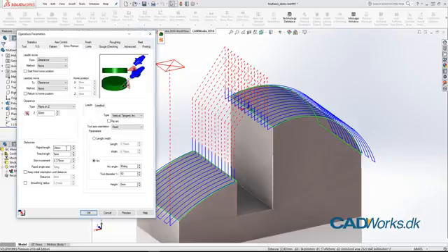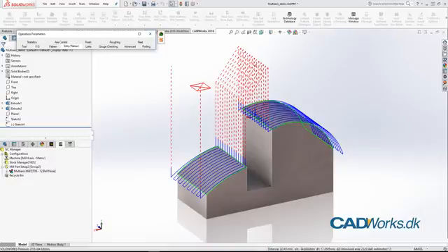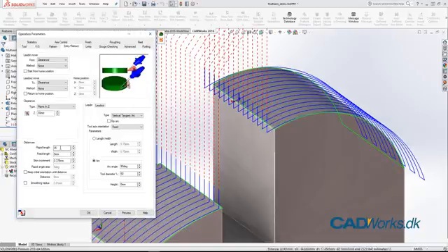That is 20 millimeter. If I set that to 35 instead, then I'm going to come up further, and then we are going to travel above our clearance plane. And this is what we expect. We are coming from this point, and then we are going to the rapid length, which is 35, from this point. So in this case, we are actually only traveling 30 millimeters in rapid because the first 5 millimeters are our feed motion. Try and explain that by setting that to 25.